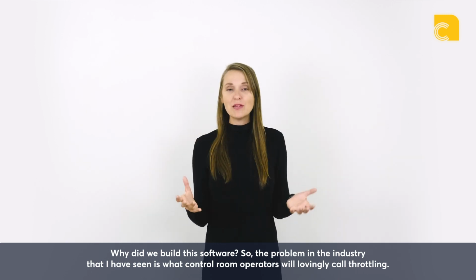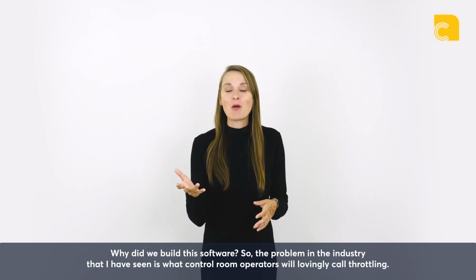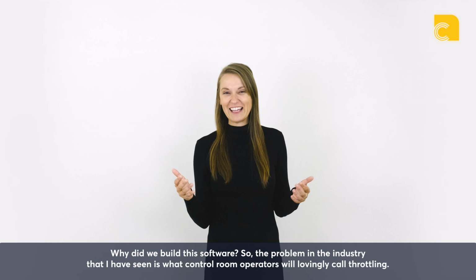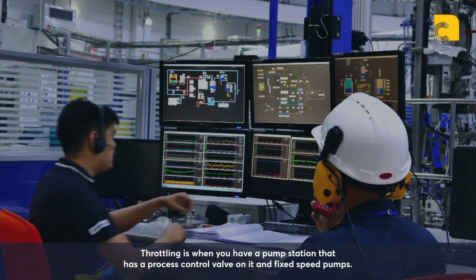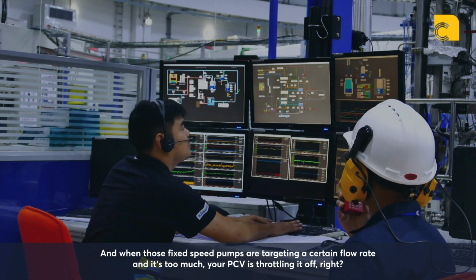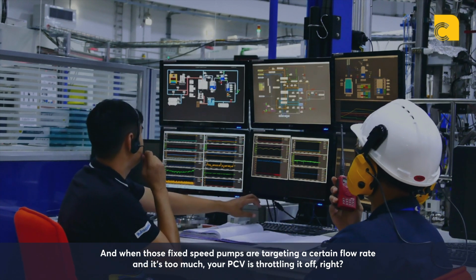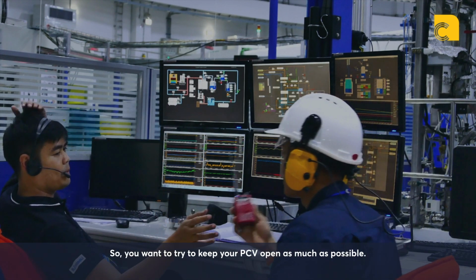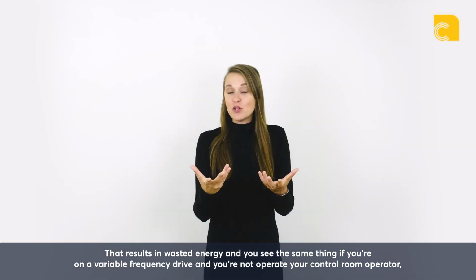So the problem in the industry that I have seen is what control room operators will lovingly call throttling. Throttling is when you have a pump station that has a process control valve on it and fixed speed pumps. And when those fixed speed pumps are targeting a certain flow rate and it's too much, your PCV is throttling it off, right? So you want to try to keep your PCV open as much as possible. That results in wasted energy.